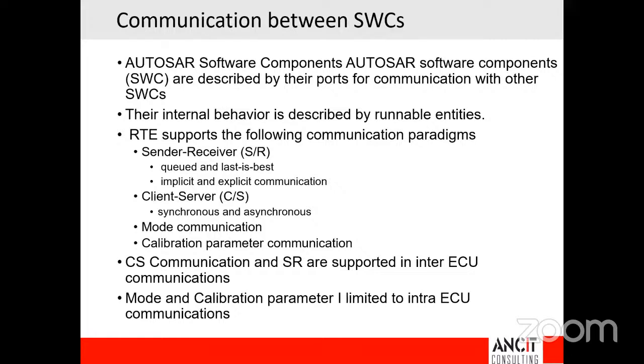Then in client server communication, we have synchronous and asynchronous communication. Synchronous is more of a blocking function, as we typically call it in embedded. You call another function, you expect the other function to return something, and till that function returns something, you are waiting for that value to be returned. That is called a synchronous or blocking function. Asynchronous is where you call the other function and then you just keep going ahead with your task.